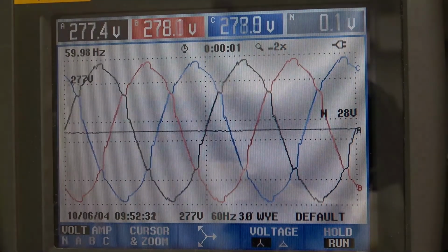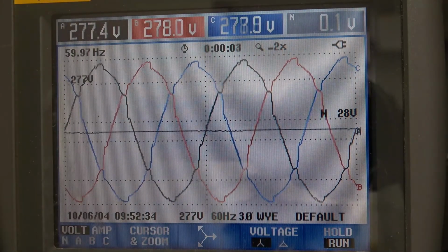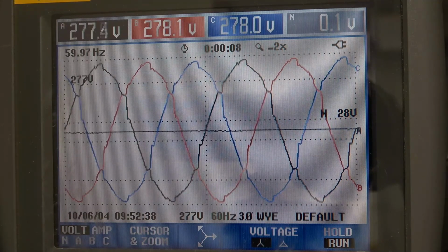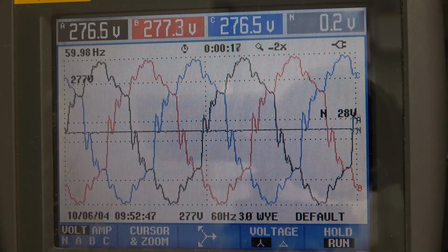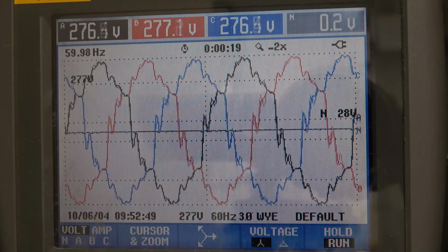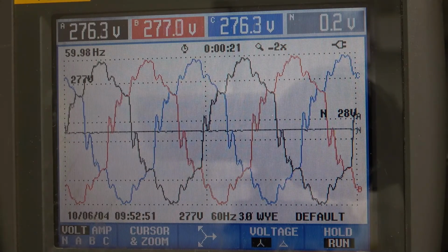Now, let's go back to the waveform and look at the voltage. As we're looking at the voltage there, you can see it is a bit distorted, but watch what happens when I switch over to my alternate source. Now my voltage distortion is much more significant, and in fact I'm getting close to those multiple zero crossings there.